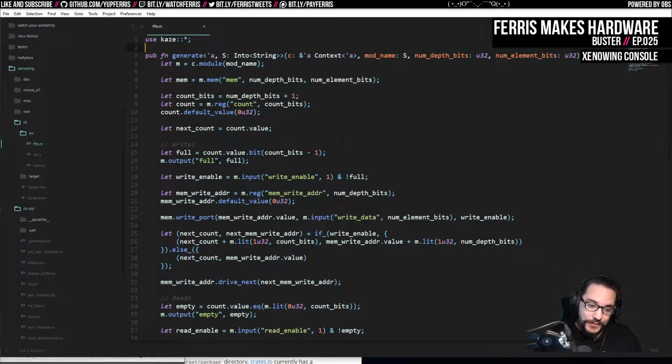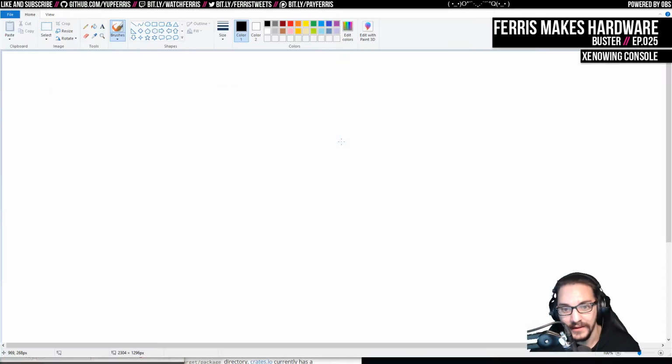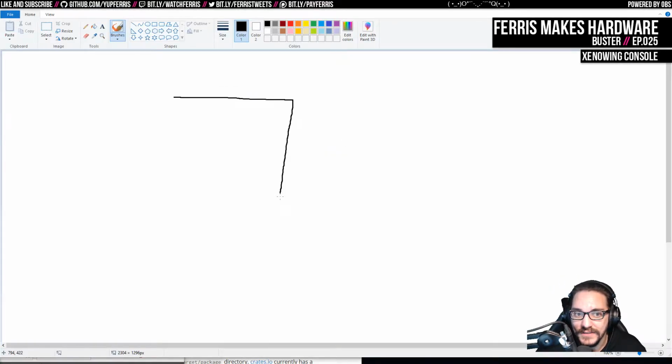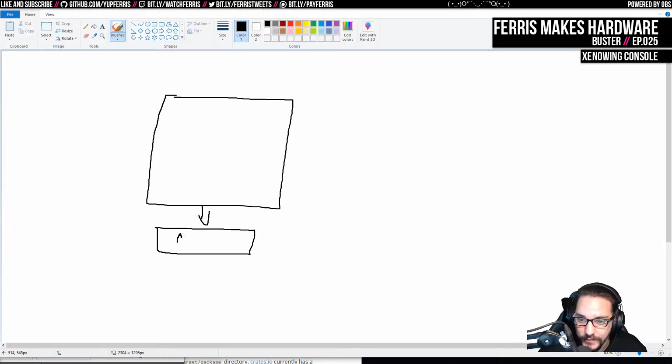But yeah, it's a really simple kind of structure, and it's pretty ubiquitous. In particular, that was something I used in the memory buses because, let me paint a little picture here, literally. If you have a system like this, and let's say this is some bus. So down here, it's going to talk to some memory, for example. And then up here, you might have, for example, display DMA or some other kind of DMA, and then a CPU. Both of these are going to be bus masters, whereas this is going to be a bus slave.